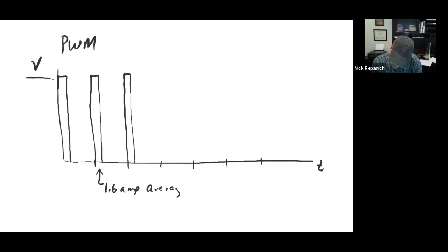This rate on the time scale, if we flip it around and put it into frequency, is probably 10 kilohertz to 40 kilohertz, which works well. You want to be above 10 or you're going to hear it buzz, because it's in the audible range. So you get it up out of 10, and those transistors can easily change at 10 kilohertz. So that might be 1.6.